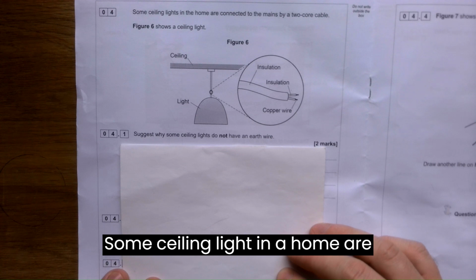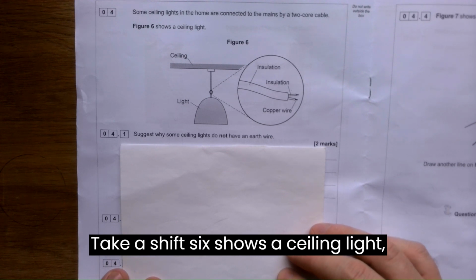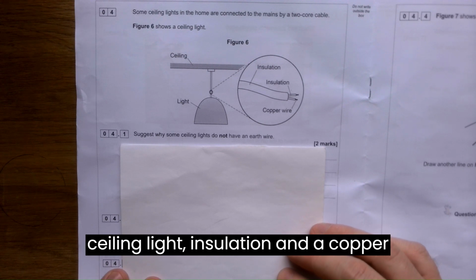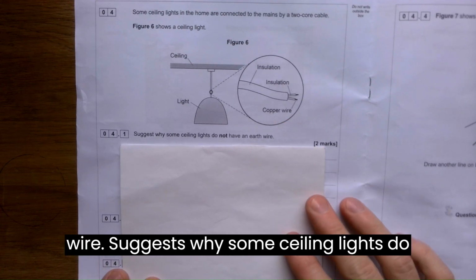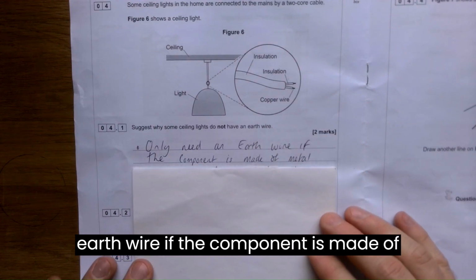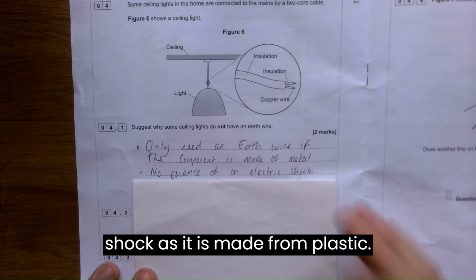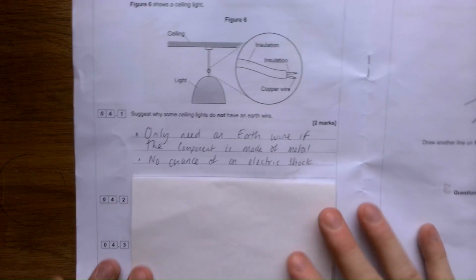Some ceiling lights in a home are connected to the mains by a 2-core cable. Figure 6 shows a ceiling light, insulation, and a copper wire. Suggest why some ceiling lights do not have an earth wire. You only need an earth wire if the component is made of metal. There is no chance of an electric shock, as it is made from plastic.